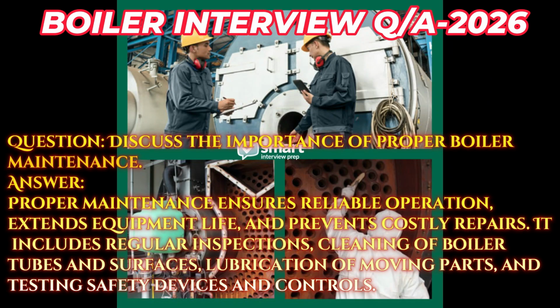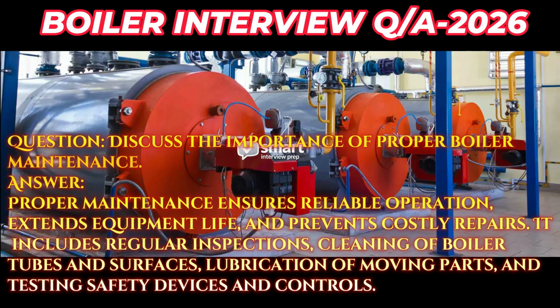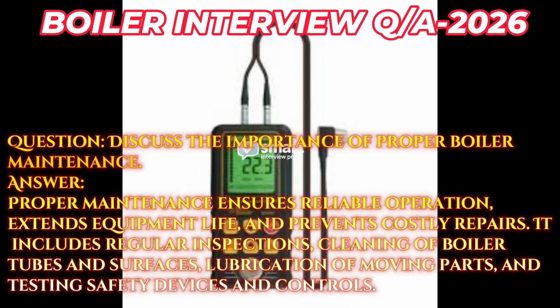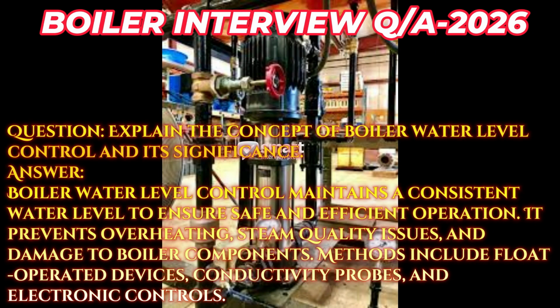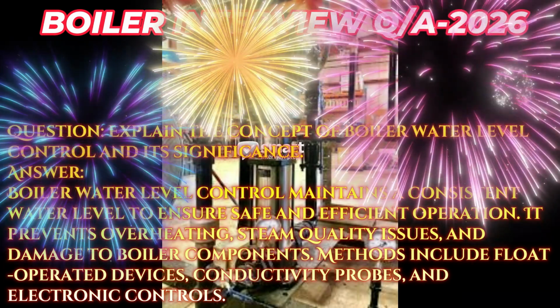Answer. Proper maintenance ensures reliable operation, extends equipment life, and prevents costly repairs. It includes regular inspections, cleaning of boiler tubes and surfaces, lubrication of moving parts, and testing safety devices and controls. Question. Explain the concept of boiler water level control and its significance.